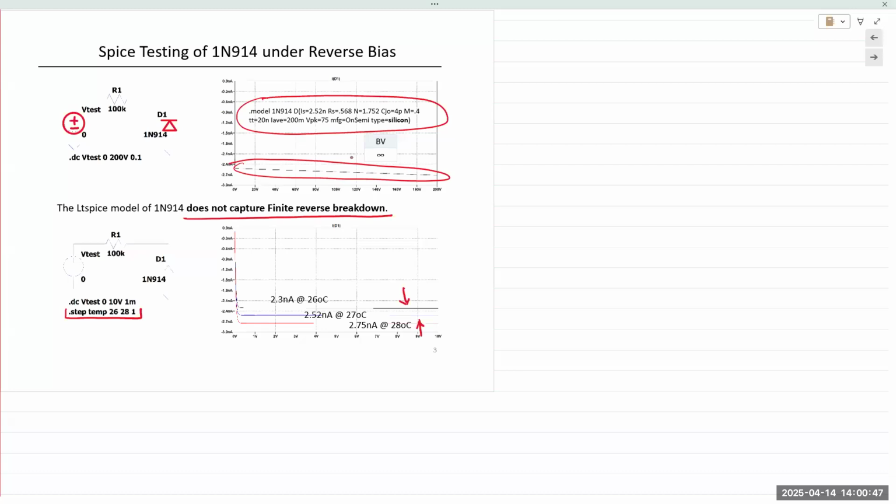It's a well-established, well-studied fact that a semiconductor is temperature dependent. And for a diode, the junction is highly temperature dependent and it's linear in relationship. As the temperature increases, the diode voltage and the diode current change accordingly, and the change is highly linear. The single most common application of this is in digital thermometers.